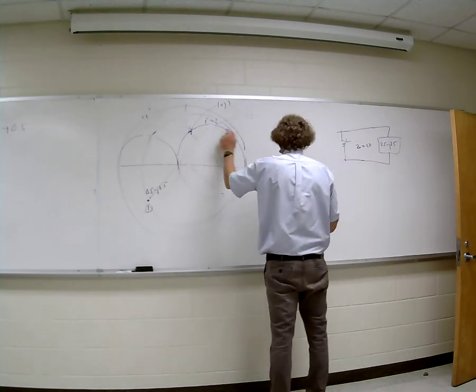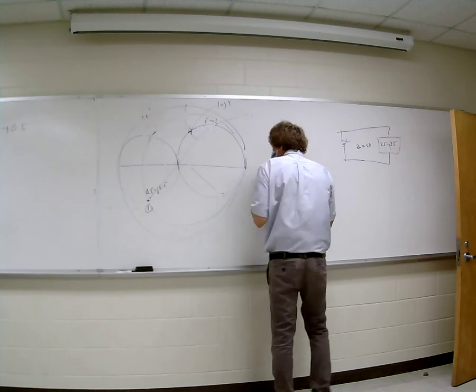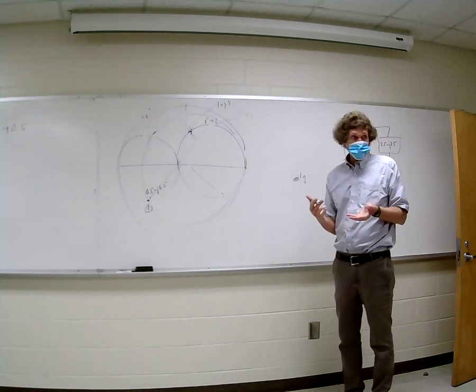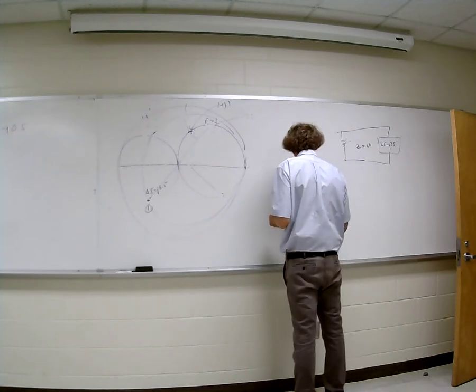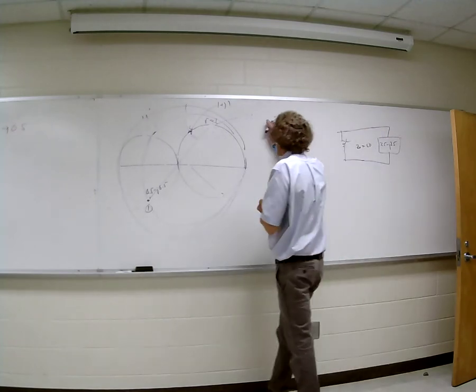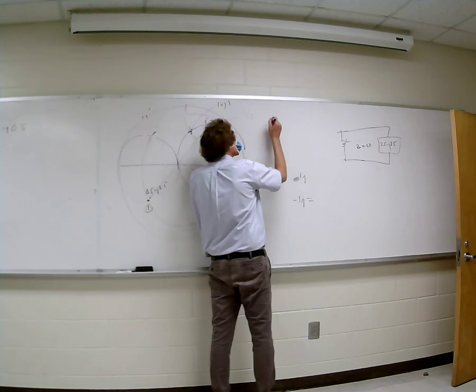So this is admittance, and I have an admittance of 1J, that's normalized. I want to get rid of it, so I want to add a minus 1J. Do you agree with that? So actually what I want to do is find minus 1J, and I want to find the value of the component.